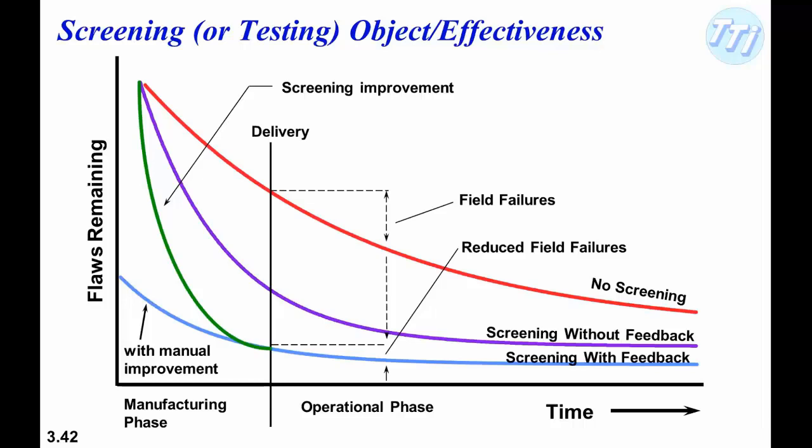And if the data acquisition systems had been operated and baked for 20 or 30 hours before they were delivered, all of these things would have been caught. As it turned out, we had a batch of bad capacitors. Every single capacitor in the system was bad. We replaced them all with a panic, everybody who could operate a soldering iron putting in new capacitors.